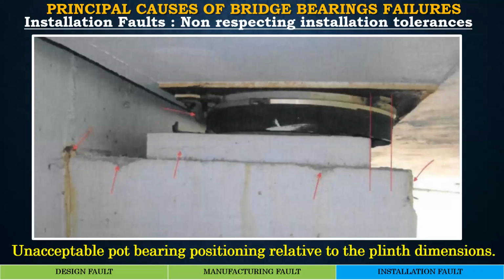This is another example of failure of non-respecting installation tolerances. It concerns a position in plane as well as the incorrect positioning in height. So if you install knowing fully well that it is not in alignment with the support, obviously it will cause failure of the pedestal, or it will cause failure of the bearing.